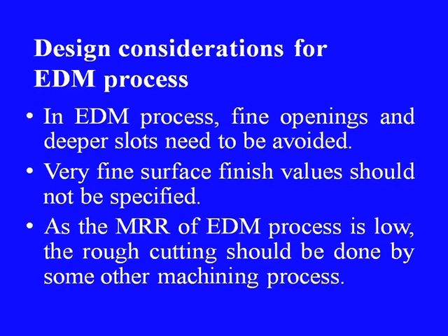Design considerations for the EDM process. In the EDM process, fine openings and deeper slots need to be avoided. Very fine surface finish values should not be specified, as we have already discussed. EDM is basically a coarse material removal process and is not recommended for fine finishing of surfaces. As the MRR, or material removal rate, of the EDM process is low, the rough cutting should be done by some other machining process.